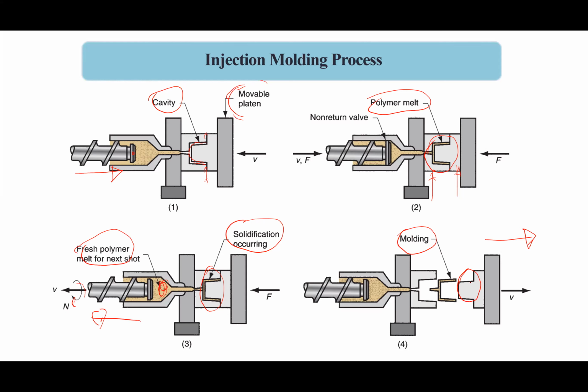to the movable platen. And how this is done? This is done by using a draft, as we discussed in the manufacturing process lectures in your undergrad. The draft allowance, that means due to the inclination of the surface, this part will actually stay with the movable platen. Okay. And when this part is staying in the movable platen, there is some ejection method available in the mold. I'll go to the construction of the mold in the next slide.